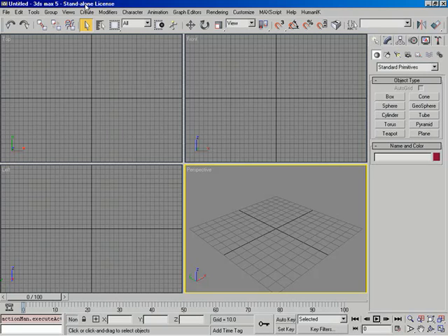So the very first thing that I'd like to do is discuss what a polygon is and what an editable poly is. Now, a polygon is basically, very basic here, just a surface that has 3 or more sides. Okay? Now, we generally refer to these sides as edges, and later on we'll be seeing how we can work with edges as a sub-object level type. So it's basically we'll be grabbing a side and moving it.